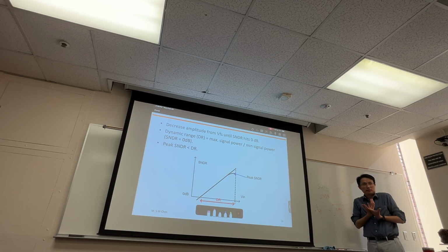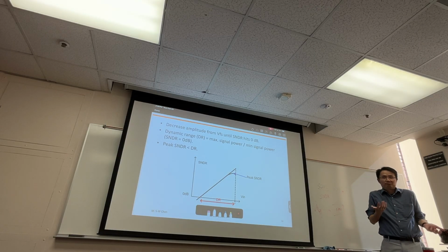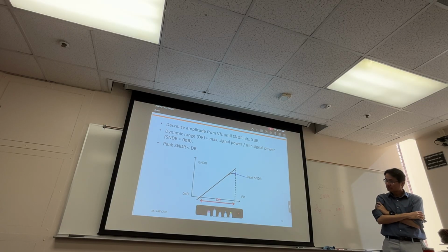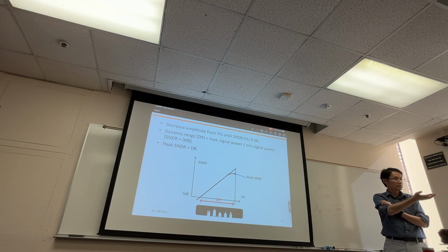Because in the end it's a ratio. If the signal increases and the noise also increases, then they cancel out. Would the noise increase? Not even proportionally, not as much. Think about it: take quantization noise. As long as your input is larger than 1 delta, the error will be more or less uniformly distributed between plus and minus delta over 2.